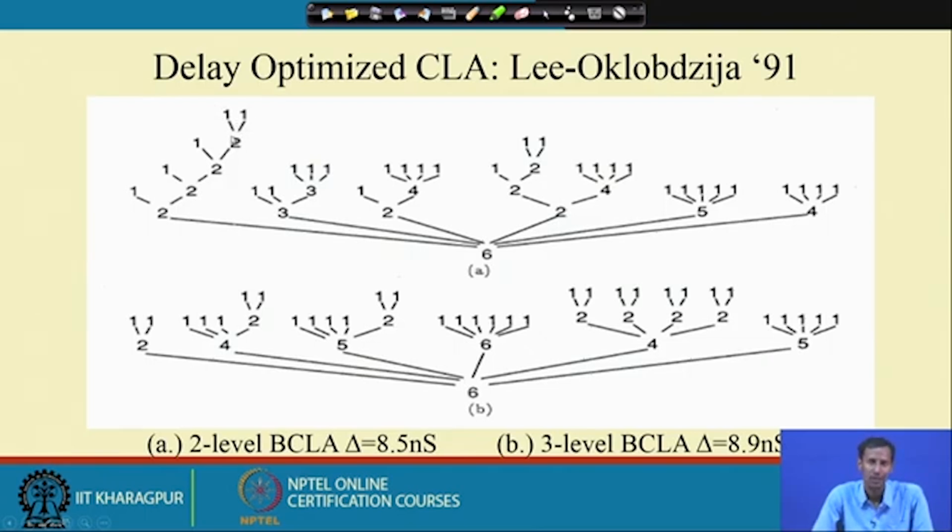Okay. So, this takes 2 input, then again 2, here is 1 and 1 coming over here, then 1 1 2, then 1 1 1, that means this is the 3 input, and then 1 1, then again 3. And finally, we are having 6 at this particular place. So, that means the maximum fan in is 6 over here.